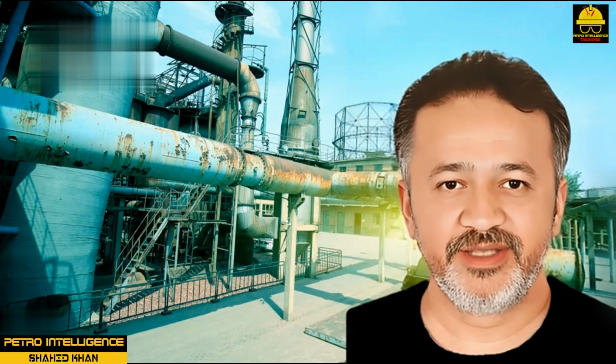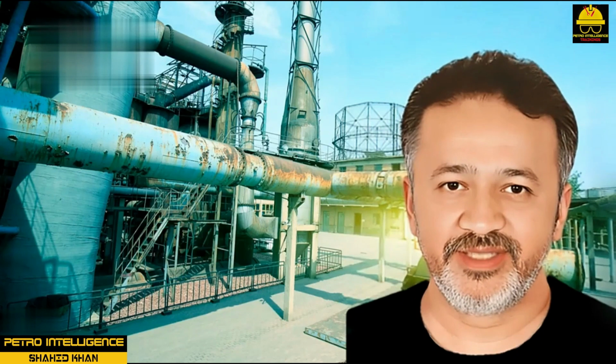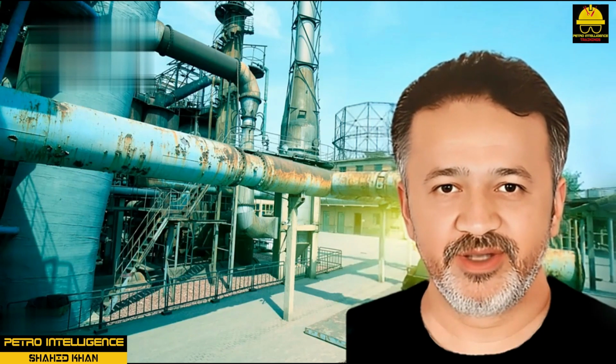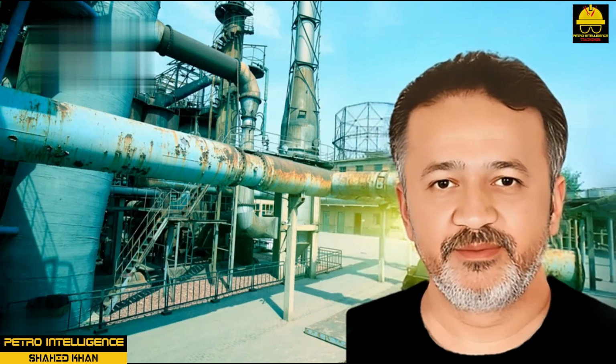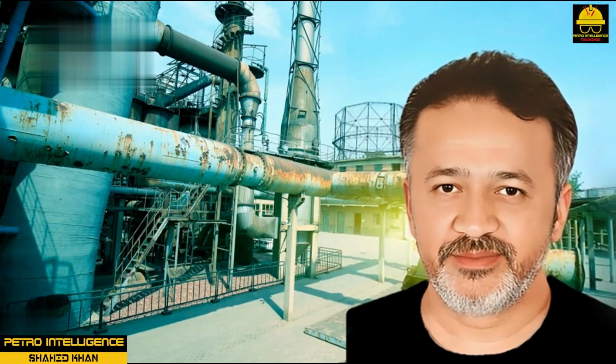The knockout drum is a carbon steel vessel that contains a steam coil to vaporize light materials and to warm up heavy materials so they can be pumped to recovery. The pump can be automated to control level but will automatically shut down on low level in the drum. Low and high alarms in the control room are normally provided.